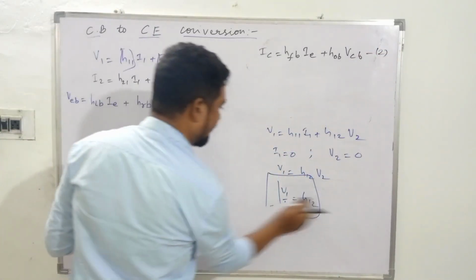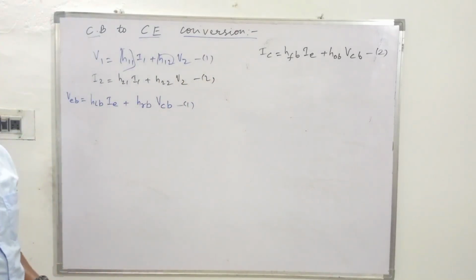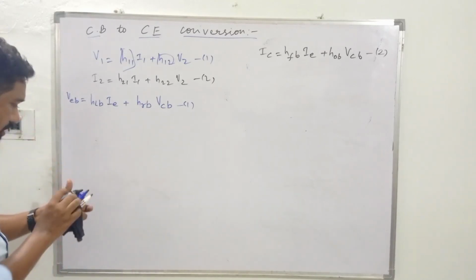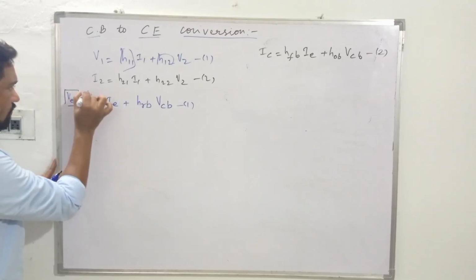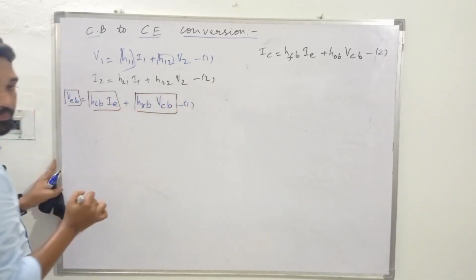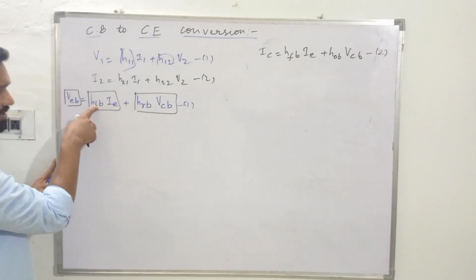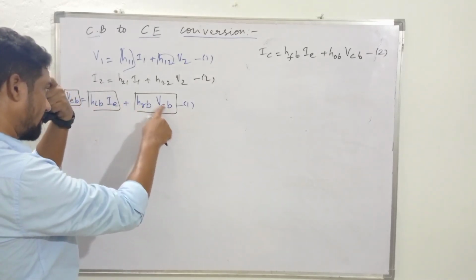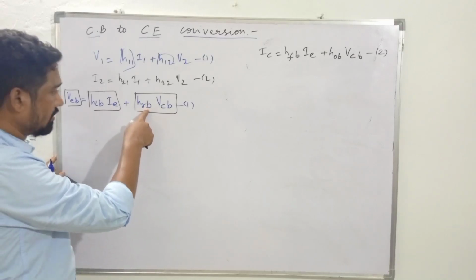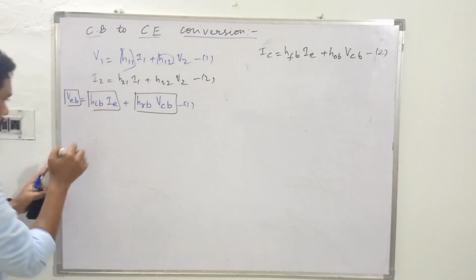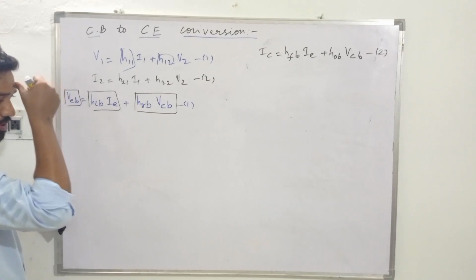Now this has to be put into a circuit hybrid representation like this one. Please watch again. It's a voltage which is equal to this voltage drop plus this voltage drop, right? So how is this voltage created? It's a current multiplied with a resistance, and straight away we have a voltage over here. Then it's a voltage multiplied with some constant, a gain. This is current multiplied with a resistance, so it's on the input side. V1 will be at the input of the two-port network.